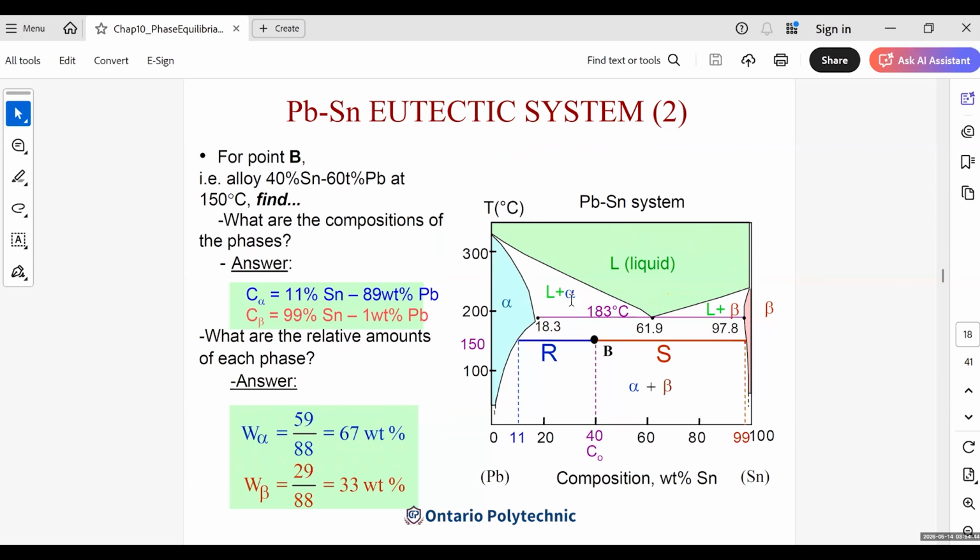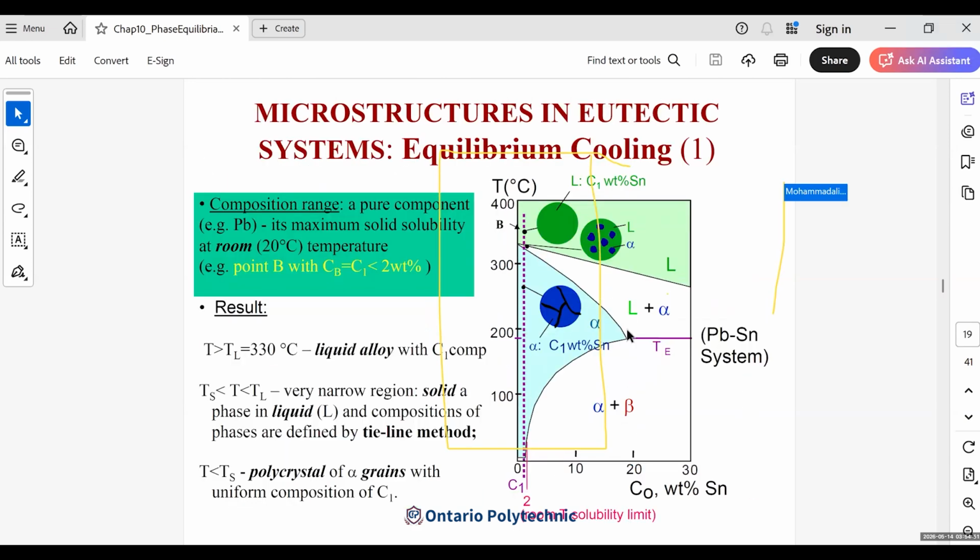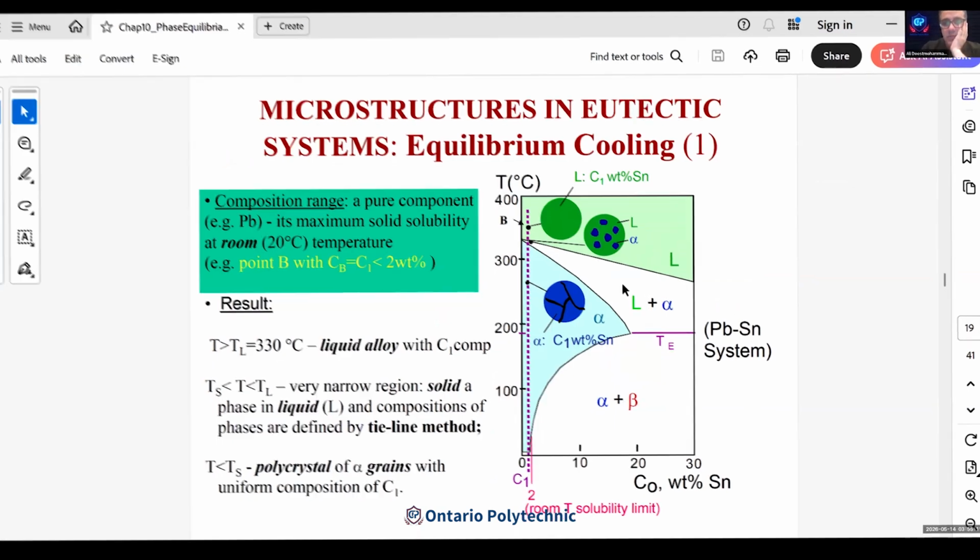Okay, imagine you're talking about this part, yeah? It's between 0 and 30%, yeah? Yes, and temperature-wise, we are more than this TE. The temperature is higher than... Oh, I see. I got that. Okay? So we are in L plus alpha region, two different phases. Okay? So two different phases, and let's get back to the...